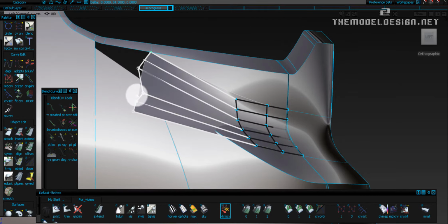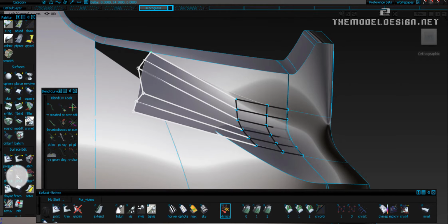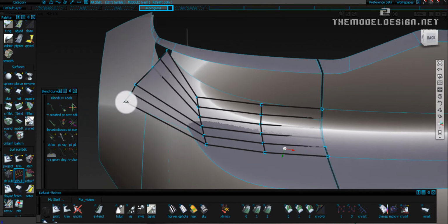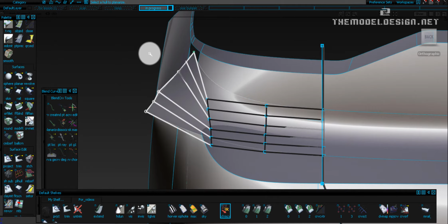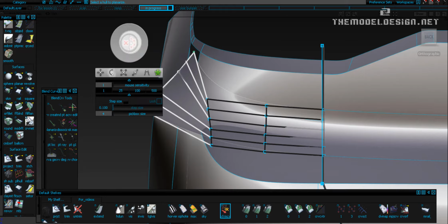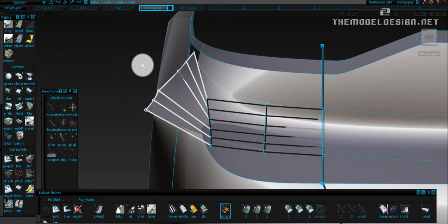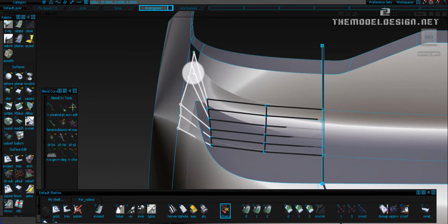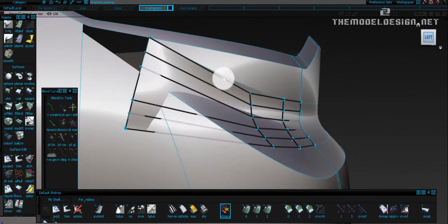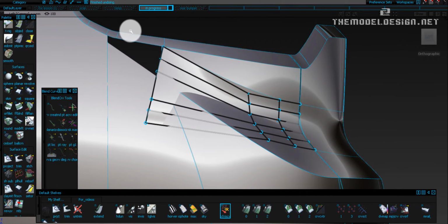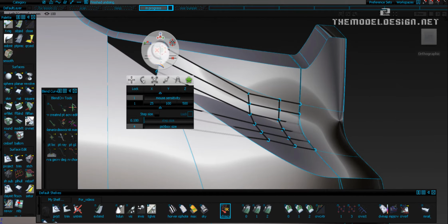With time passed and more experience, you will become more and more spontaneous when coming up with new ideas for CV manipulation. Don't worry too much about any sort of surface continuity at this stage. Just make sure that CVs are neatly distributed within the patch. A good-looking surface can always be aligned later in the process. If you don't get a good CV layout at this stage, you won't create a decent quality surface and will be wasting your time in later stages of the modeling.